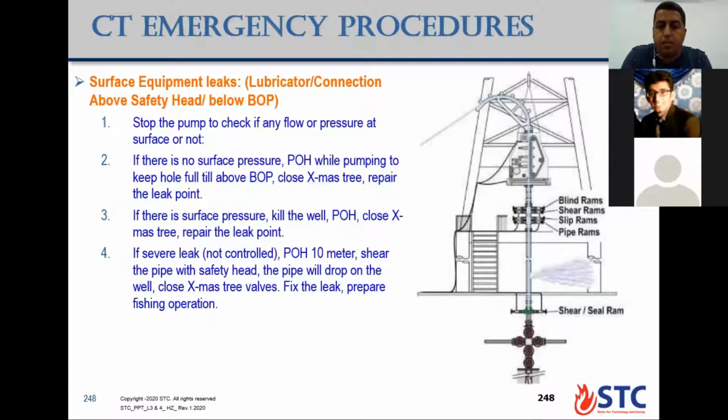Okay, the answer starts from pull out of hole. Pull out of hole 10 meters, shear the pipe with the safety head, and the pipe will drop on the well. Which option will we take?